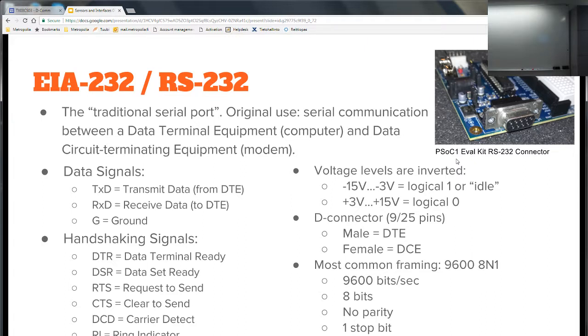The voltage levels are not the same as the TTL levels, the standard logic levels. Most processors which have a serial port can actually tolerate those voltages as input, and of course they send from 0 to the power supply voltage as output, and most of the input buffers can use those signal levels too, if it's say 90s technology.